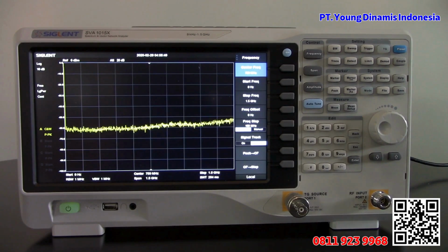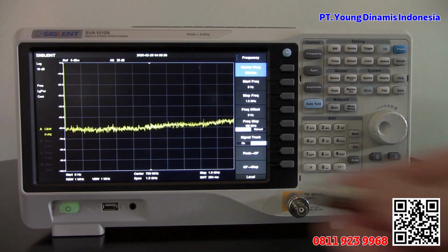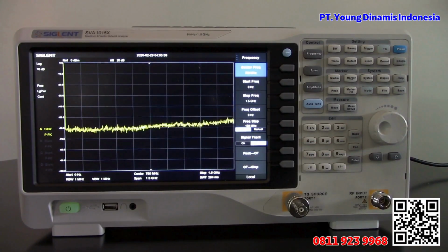It's actually quite good at determining where particular faults develop over time as the impedance changes between connections. Let's say you're using a barrel adapter or some type of connector, and as it corrodes, it's going to change the impedance, and then that could cause signal issues later on. So the distance to fault can help you troubleshoot that particular line and determine where those faults might be. Maybe the insulation has worn away and you're losing some of the conductivity on that cable due to corrosion again, or you have a break in the actual cable.